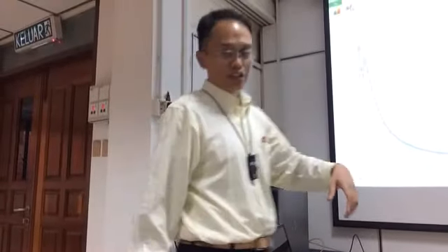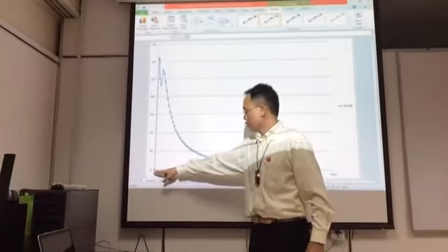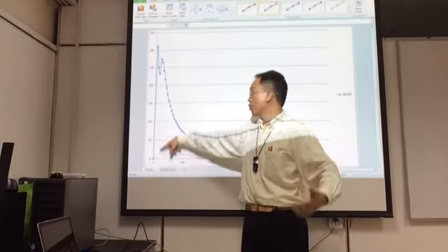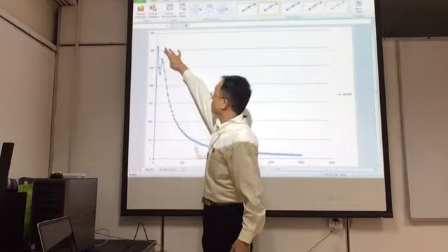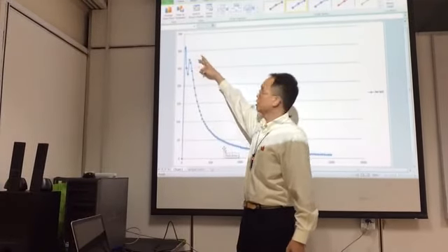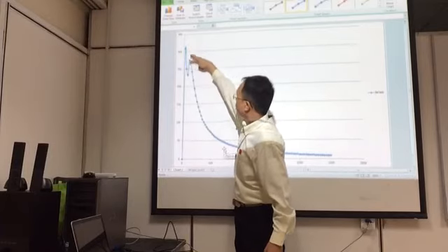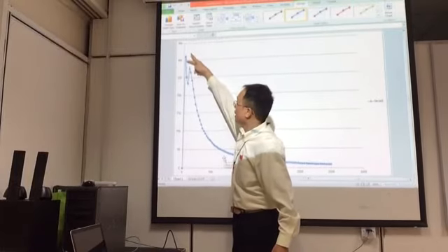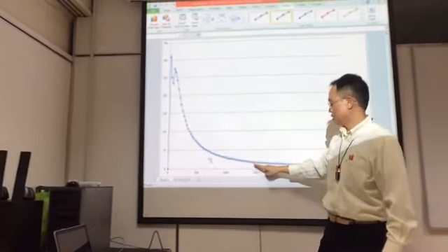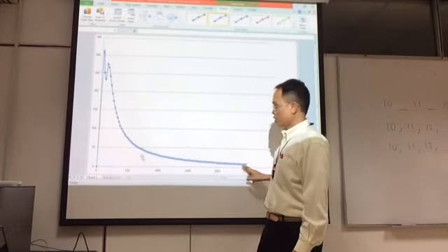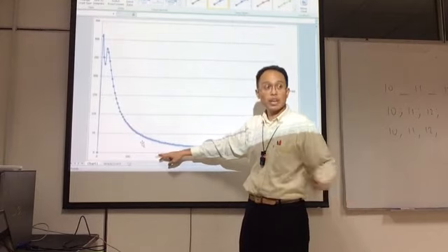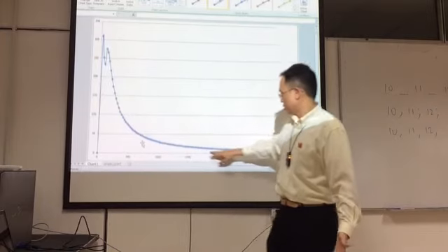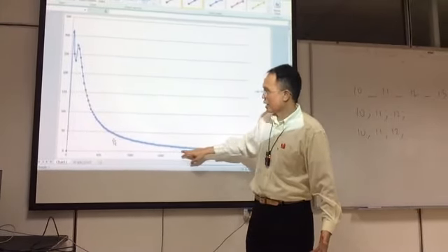So here it shows the concentration with distance from the stack. At 0, you cannot model the concentration at the stack point. It has to go a certain distance before you get a concentration value. So there's a bit of instability in the modeling results. It's maximum there and then decreases and increases. I feel that this is not really correct. It's uncertainty there. It should be somewhere in the middle. And then as it goes away from the source, the concentration decreases by this value. So at 1 kilometer away from the source, directly downwind, it's at about 20 to 30 micrograms per meter cube. But further away, it balances out at around maybe 10 micrograms per meter cube.